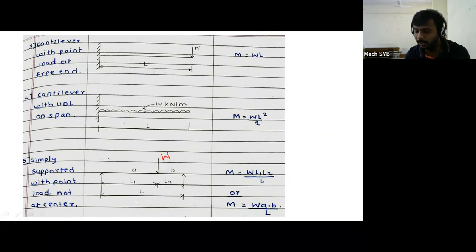So below this list of formulas, write down one sentence. It is very important. While calculating bending moment, capital M, if the beam is subjected to UDL, don't convert it into point load.